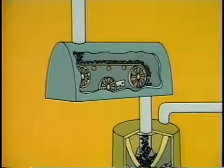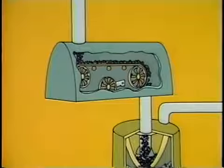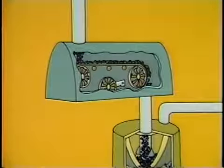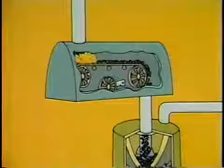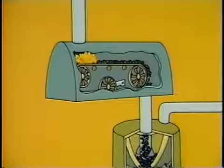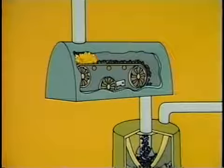In most cases, a feeder doesn't catch fire all by itself. Feeder fires usually result from burning coal being transferred to the feeder from the bunker. Symptoms of a feeder fire include smoke coming from the feeder and hot metal surfaces.